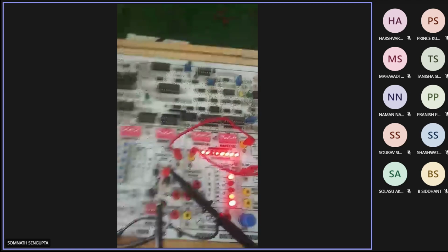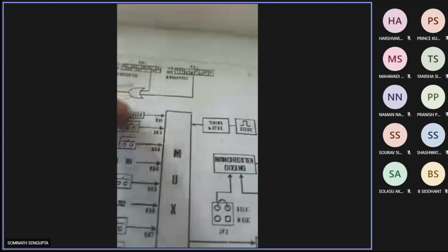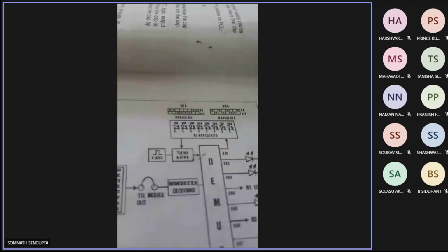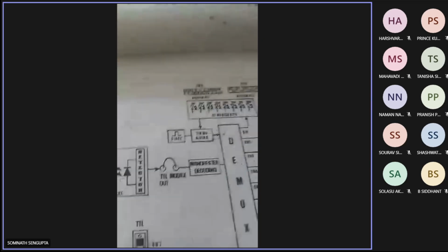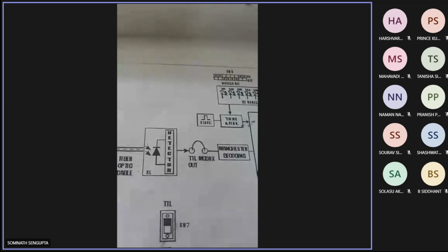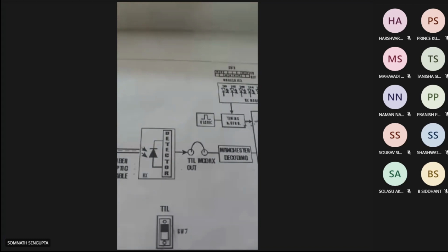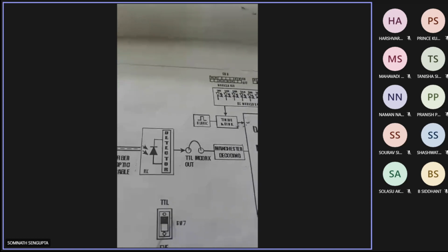It is also mentioned in the manual. You can see in the manual that the marker settings are achieved by data from two switches, and the marker setting for transmitter and receiver must be the same, otherwise it cannot distinguish or match. The receiver should have the same marker setting, so that when it compares its own marker settings with the incoming data frame, it will understand that it is the starting of a frame.